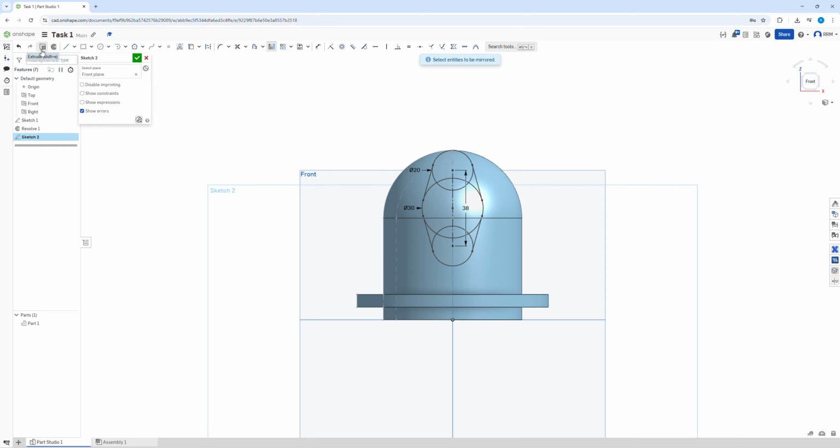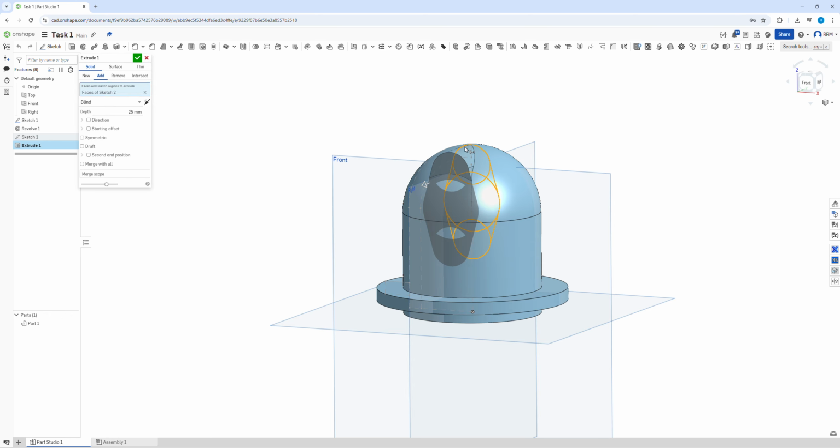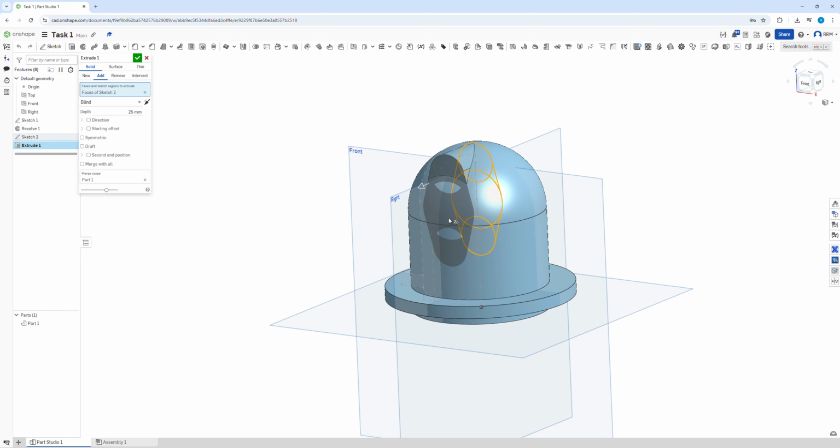We're now going to extrude this out, so click on extrude at the top, or Shift E, and move it around. We want all of it selected. It's not selected everything, so just drag it over, and it will select it all.